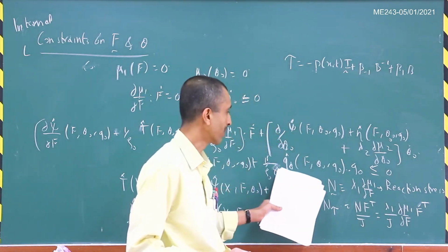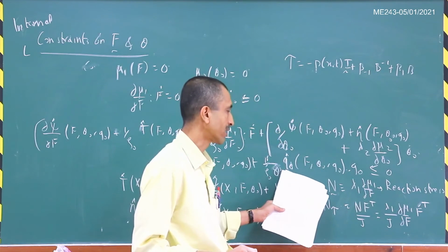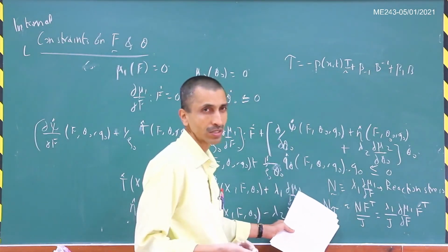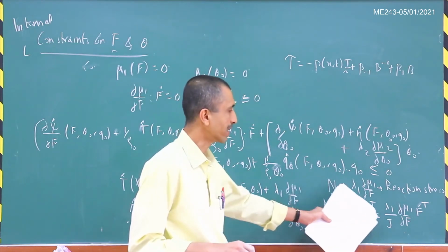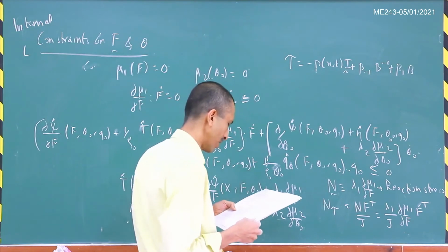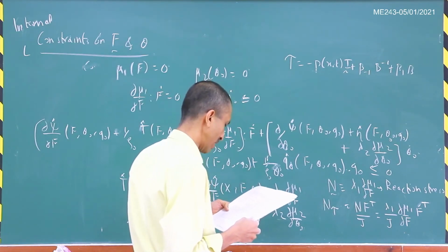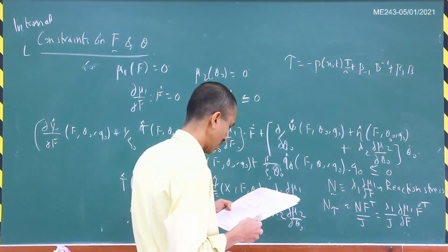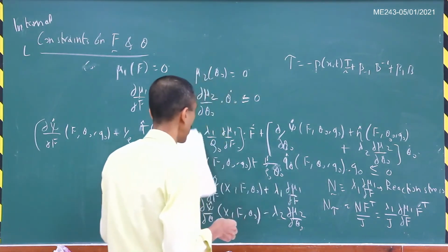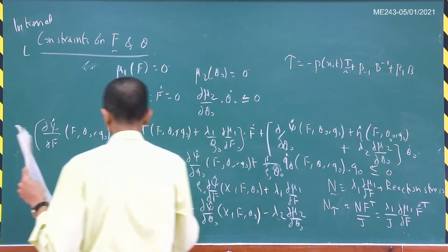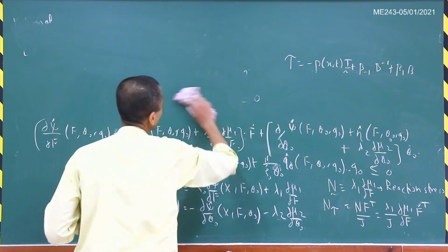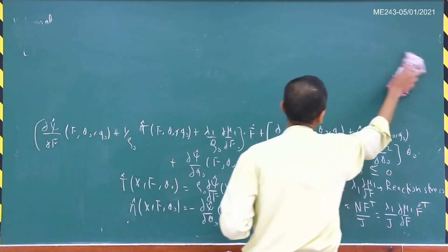Okay, so first we deduce what is the reaction stress for the first order of stress, and then from that n tau, because tau is the Cauchy stress, that is the reaction stress now for the Cauchy stress here. Fine, and so let us take an example here, but before that, I have considered only one constraint. If there are multiple constraints, then let us look at what happens. It's a fairly straightforward extension for multiple constraints.